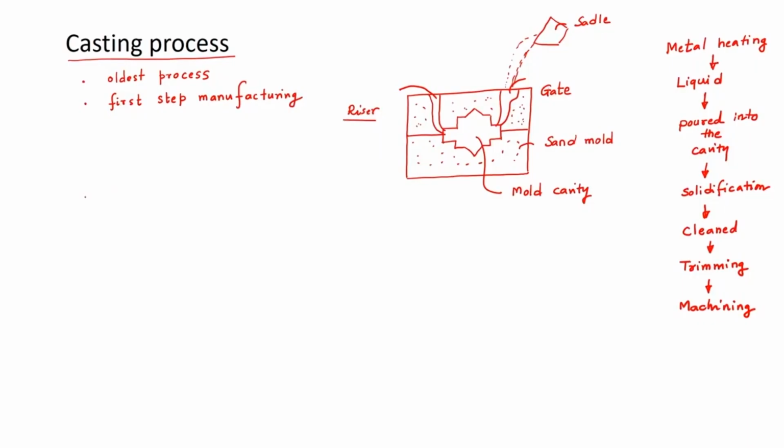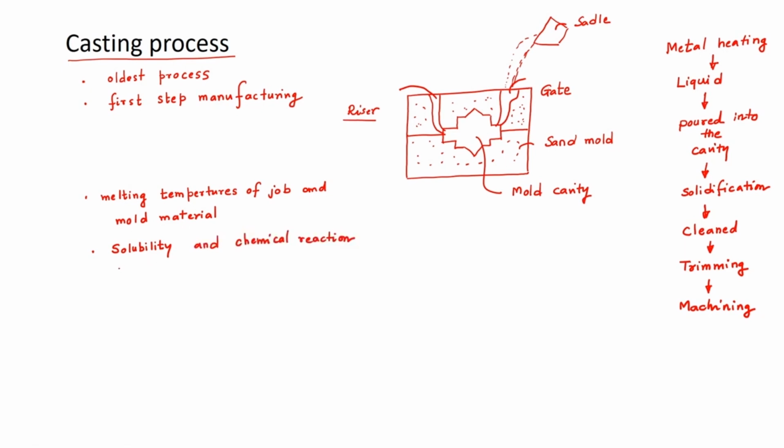The designer or the process engineer should know about the melting temperatures of the job and mold material, then solubility and chemical reaction between the job and the mold materials.